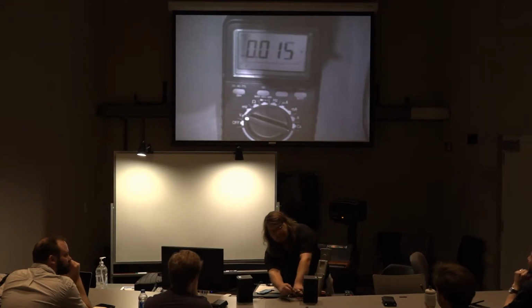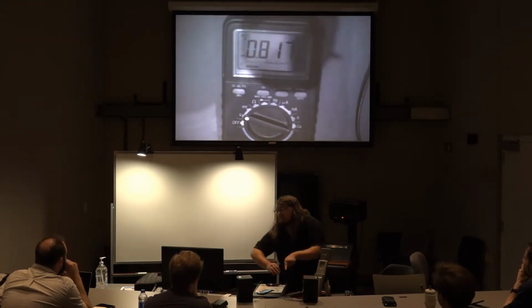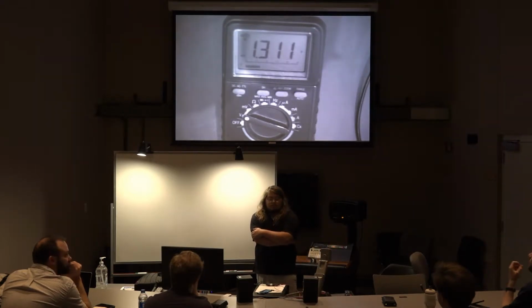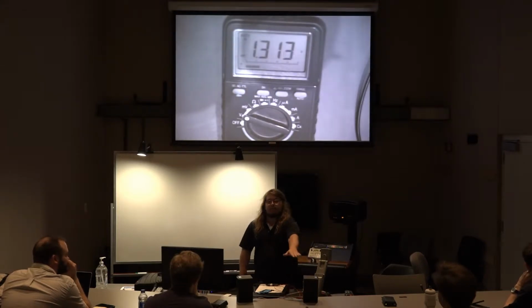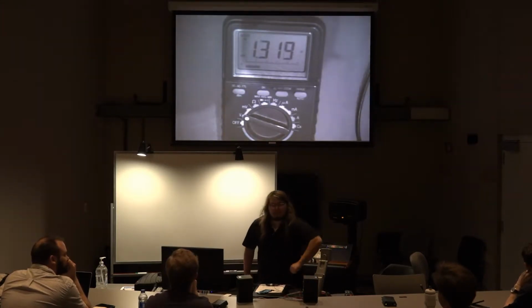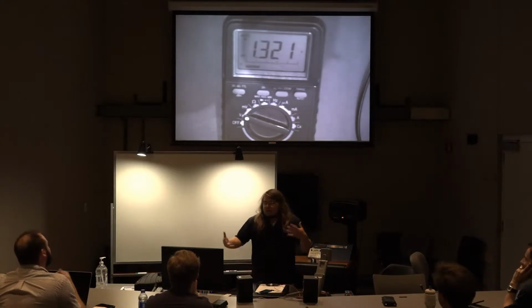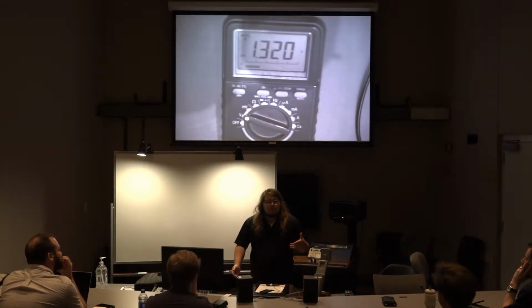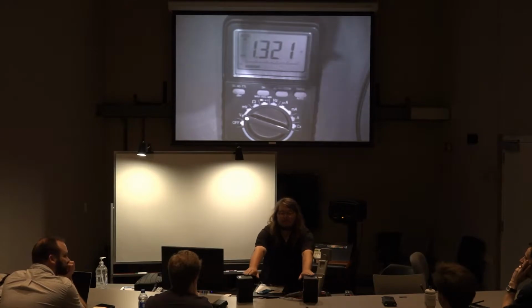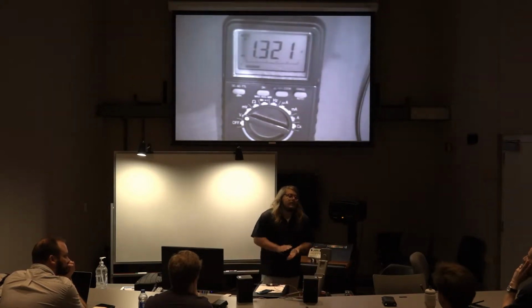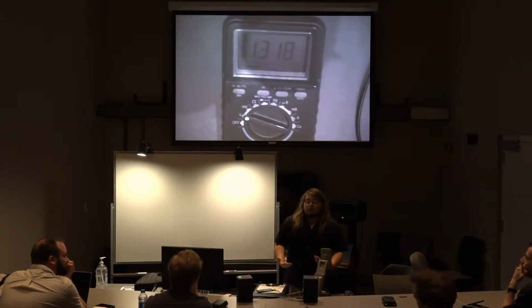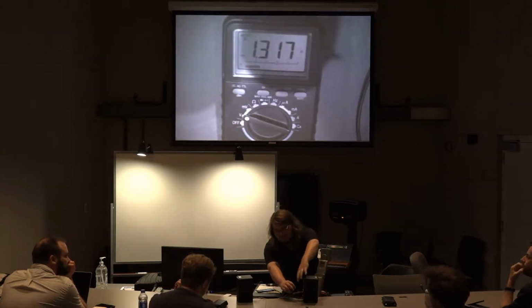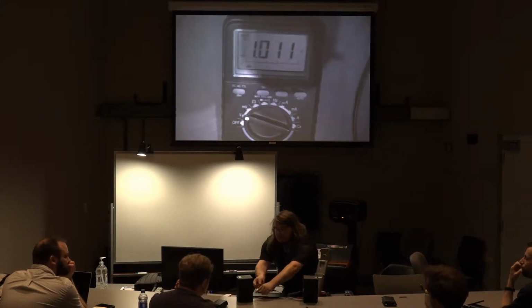That's a good question. So, what happened to the voltage on this speaker? It's reduced by half, effectively. Okay. So, intuitively, what could we say maybe about these 2 speakers? We know that the voltage just dropped in half. Twice the resistance. Okay. So, if we have twice the resistance, now, let's observe something else then.